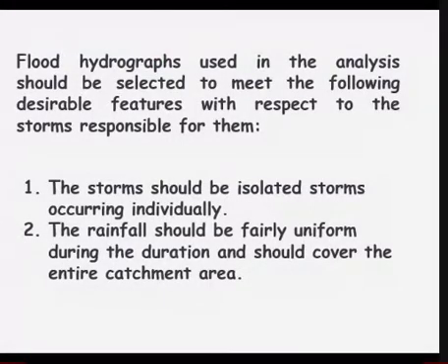Flood hydrographs used in the analysis should be selected to meet the following desirable features with respect to the storms responsible for them. 1. The storm should be an isolated storm occurring individually. 2. The rainfall should be fairly uniform during the duration and should cover the entire catchment area.